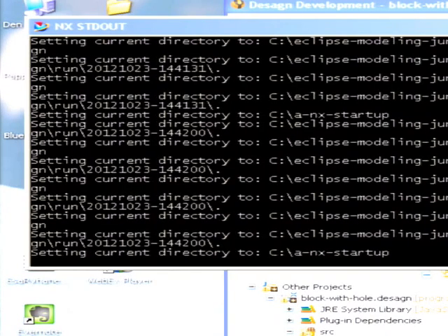And these geometries, they are parametric, as they're called. So they are controlled by expressions in the CAD system. So for example, I can change the diameter from 20 to 50. That is like the basics of this. So modeling in the way we are doing is like modeling with Lego pieces, except that we have rubber Lego, so we can resize our Lego pieces. So these are like the models.